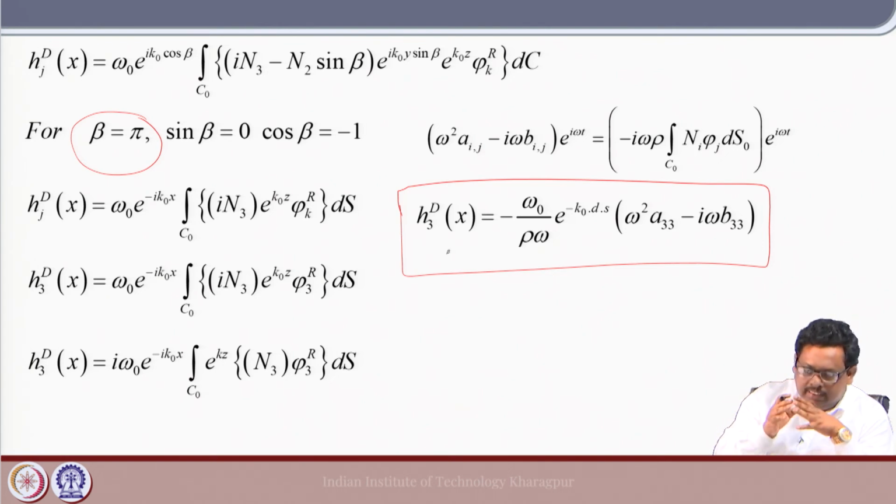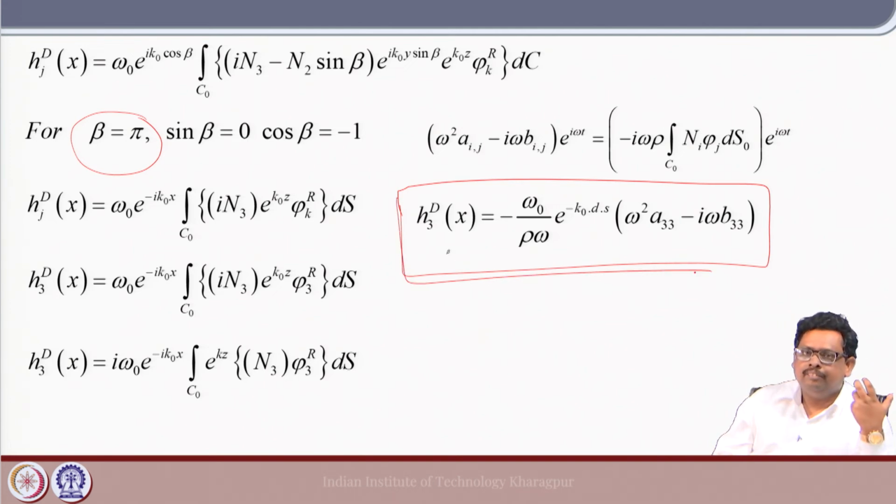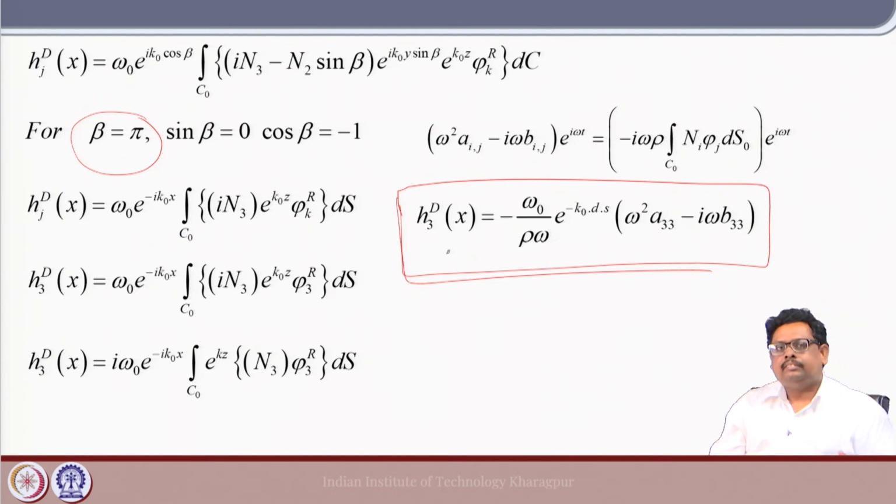So, in case of seakeeping, if you try to figure out heave, pitch, coupling, etcetera, then beta equal to pi is the most crucial heading angle, and in that heading angle I can get this diffraction force in a much simpler way. Okay. Fine.